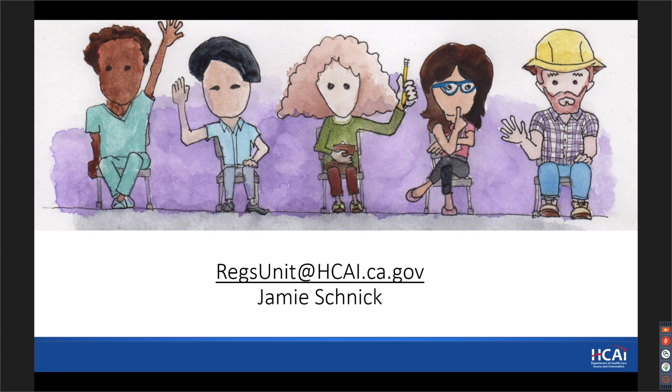So the answer is yes, you could have that installed, but when I said you should, the code actually requires that you provide protection to avoid leaks if you have fire sprinkler pipe at 6 feet 6 inches above your equipment. Hope that answers the question.